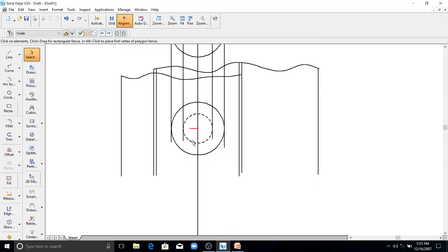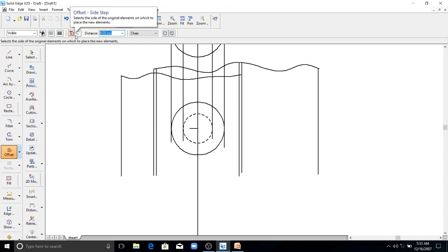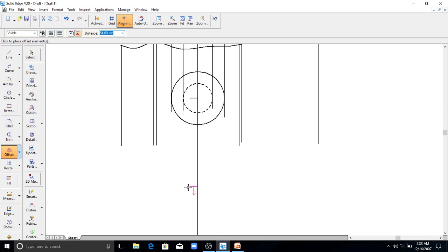Now you have to draw for a pitch distance. Pitch P is given by 3 times the diameter, that is 54 mm. So now you have to leave a distance of 54 mm. This is your new distance. This distance is pitch, that is given by the formula pitch P equals 3 times the diameter. This is the distance for new center.